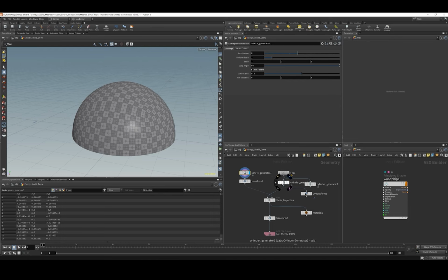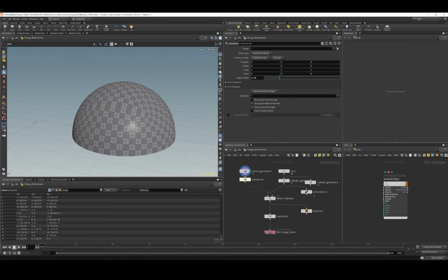So instead, I've always done this shrink wrapping technique to shape cylinder meshes to a different mesh that I want. So if it's not a sphere or it's something else, you can still have those scrolling UVs in the X and Y direction, but you can shape it to a different mesh based on your needs.